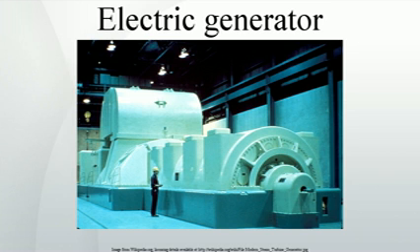Very large power station generators often utilize a separate smaller generator to excite the field coils of the larger. In the event of a severe widespread power outage where islanding of power stations has occurred, the stations may need to perform a black start to excite the fields of their largest generators, in order to restore customer power service.